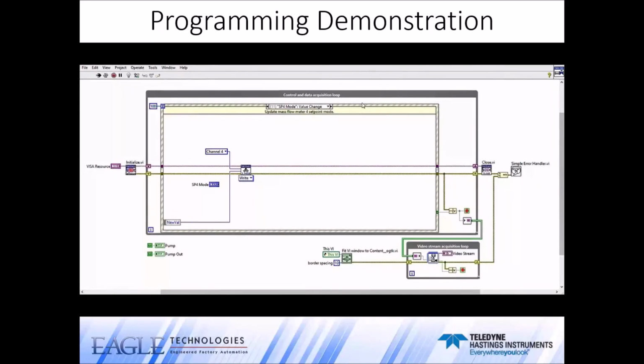Although out of the reach of our demo, we also have a parallel loop that runs the NI Vision Acquisition Assistant to provide the video stream and a stream channel writer and reader to share the value of the stop variable among both loops. When the stop button gets pressed, an event is triggered, stopping both while loops and executing the close connection VI. If there was an error during any part of the code, the simple error handler VI should show a prompt on the screen for user acknowledgement.